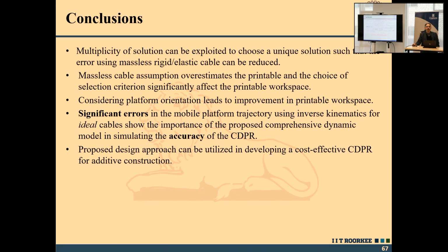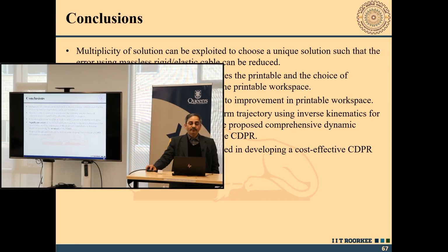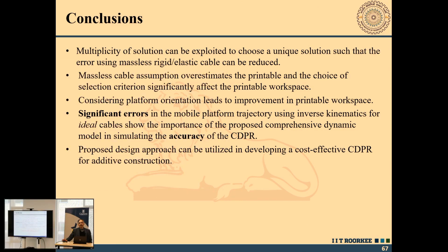To conclude, multiplicity of solution is a great challenge basically, and one can exploit it to choose a unique solution such that error using massless, rigid or elastic cable can be reduced. Massless cable assumption overestimates the printable workspace, and the choice of selection criteria significantly affects the printable workspace. Considering platform orientation leads to improvement in the printable workspace, as I discussed.